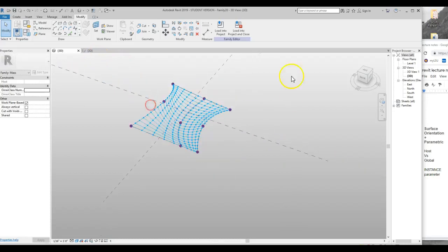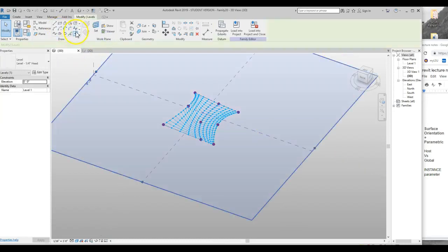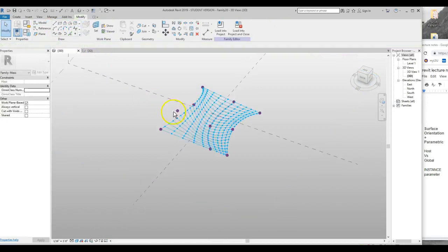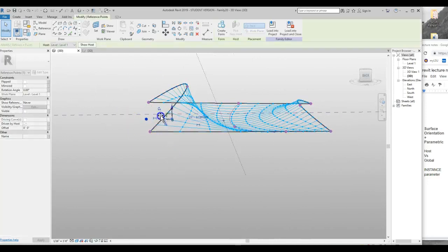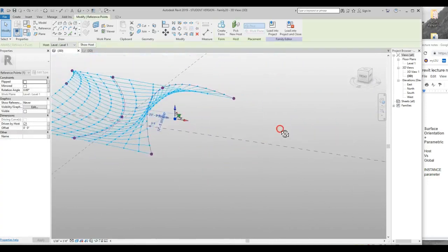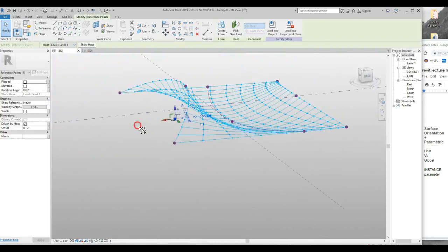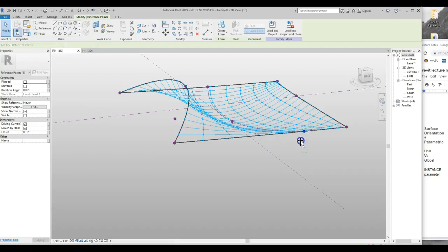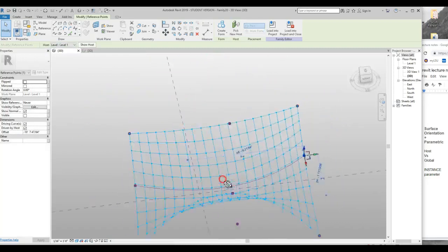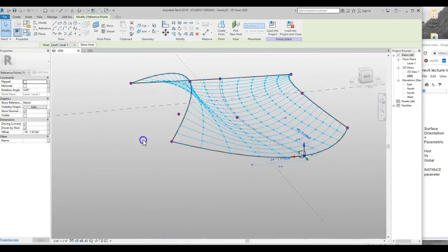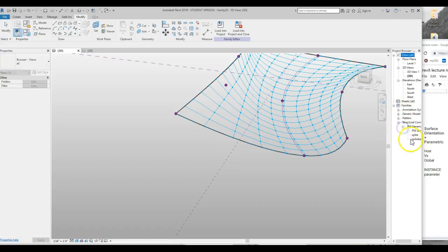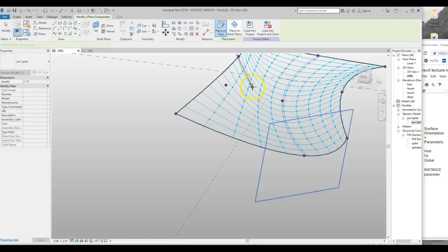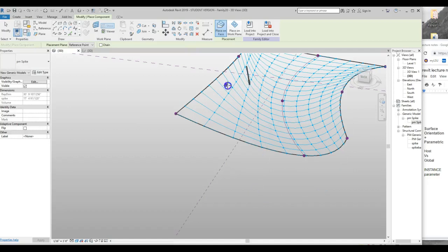So we actually have to put, I'm just going to set on the work plane here a point, and this is going to be a control point for us. See, it's on the flat surface, right around here. I'm just going to put it right underneath here. All right. So now what we want to do is bring in my structural column, PMT generic, and I'm going to grab one of these, and I'm going to grab that.